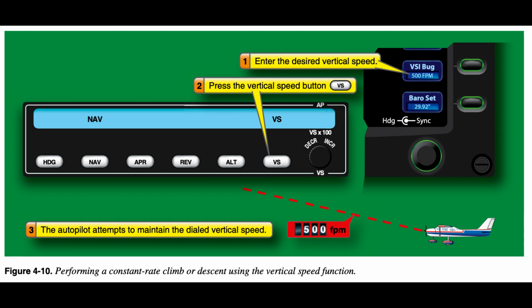If an altitude selector is not installed or functioning, the pilot has the task of leveling off at the assigned altitude, which requires monitoring progress and manually engaging the autopilot's altitude hold function once the aircraft reaches the desired altitude. You must be very careful to specify an appropriate vertical speed, as the aircraft will fly itself into a stall if you command the autopilot to climb at a rate greater than the aircraft's power plants are capable of supporting.